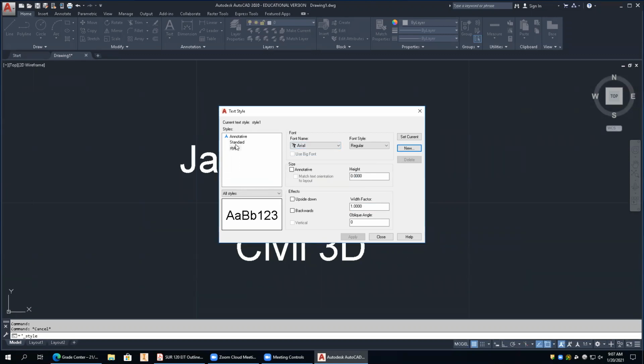So what we need to do now is go to a font. Let's grab one called Simplex. This is one I use a lot for engineering purposes. It's a real straight block letter, very nice for little simple stuff. It should look like that. Notice it is a shape file. That grays out. So unless we're doing something else, we're going to leave this all alone.